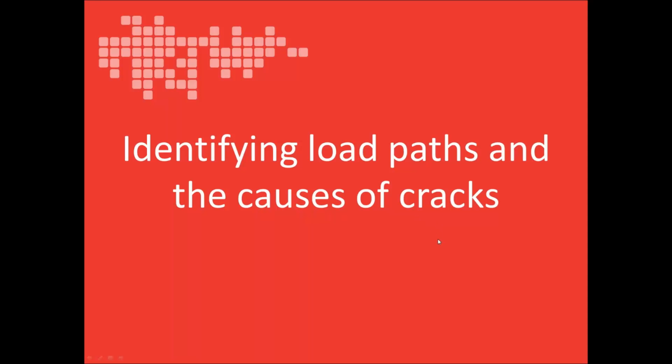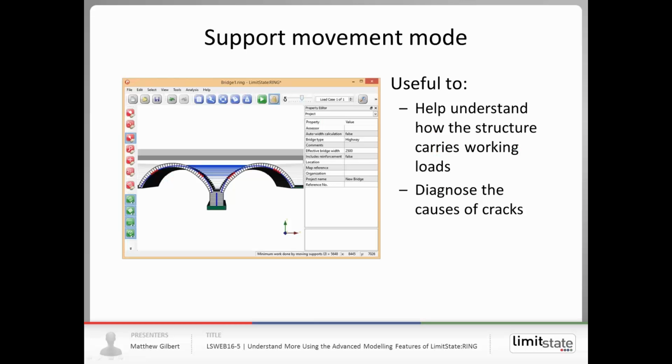Now move on to identifying load paths and the causes of cracks. So as I mentioned at the start, we explore both of these two issues using what we call support movement mode in the software. So we use it to help understand how the structure carries working loads or service loads, and also we can use it to diagnose the causes of cracks.